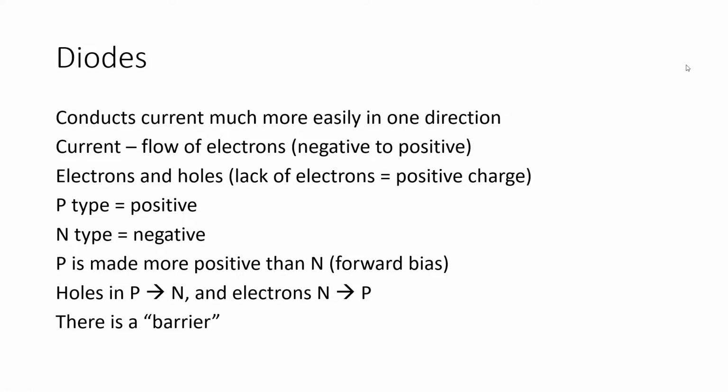Now this would be, because now you have fewer electrons, positive. This is a p-type because boron is in group 3. So therefore overall, it is more positive. For an n-type, you would need to add, for example, phosphorus to silicon because phosphorus is in group 5, and phosphorus, because the atom has an extra electron compared to silicon, has more free electrons.